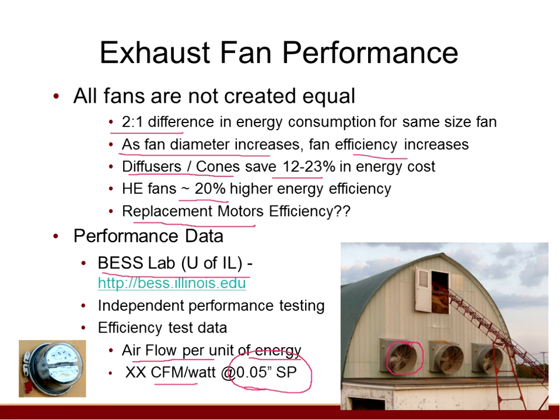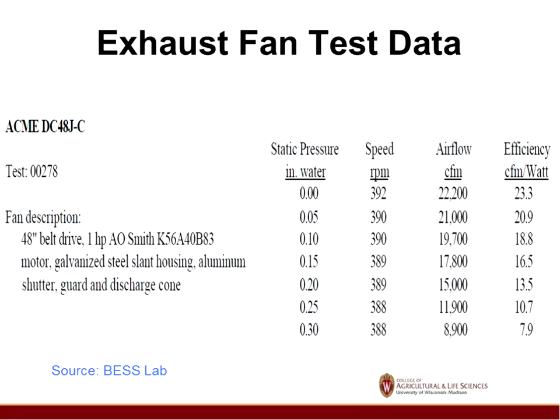So at times, even though a higher efficiency motor is going to be more expensive because it has more copper in it, it's usually worth going back to the manufacturer to get a replacement motor, or at least making sure you have a similar efficiency if you go to a motor dealer and buy that.